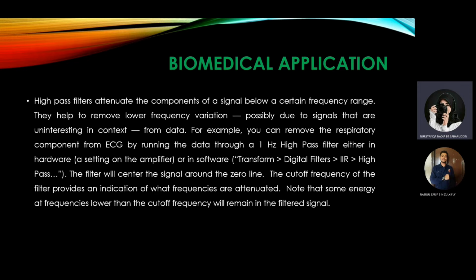Digital filter IIR high-pass. The filter centers the signal around the zero line. The cut-off frequency of the filter provides an indication of what frequencies are attenuated. Note that some energy at frequencies lower than the cut-off frequency will remain in the filtered signal.